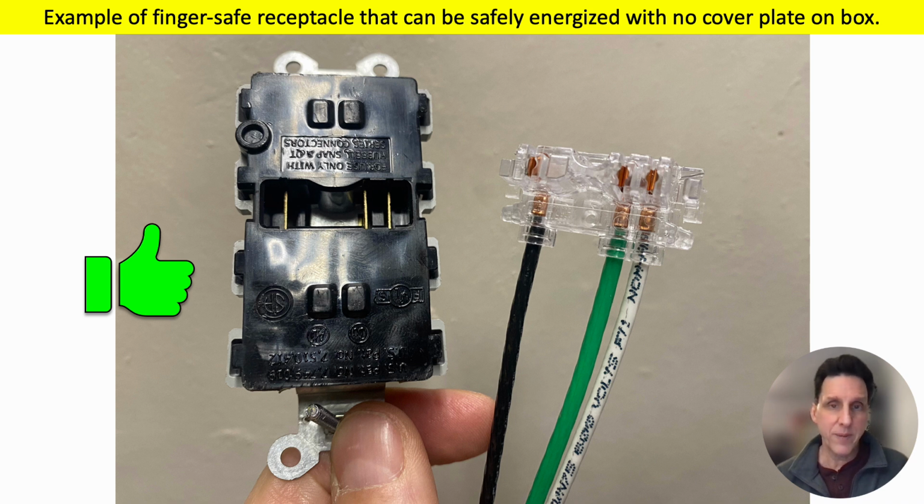Putting the cover plates on is kind of a pain in the butt because things have to be painted and they don't want marks where the covers are. So you don't want the covers on when you're painting, really. But it's a shock hazard if there's exposed energized terminals. So these are the types of devices that you'd want to install. And then you don't have to worry about putting cover plates on to energize the wires. Hopefully these changes go through. I think it'll make it a little easier for installers for temporary wiring and using the permanent wires for temporary power in 2026 and future.